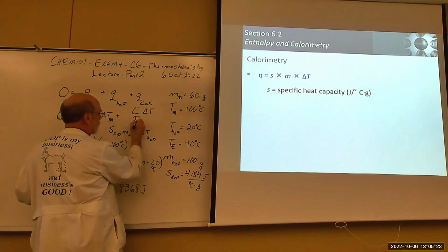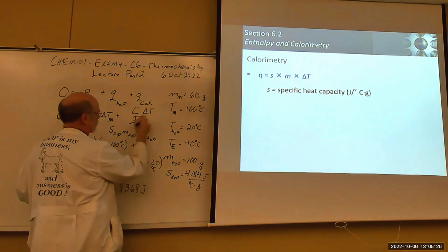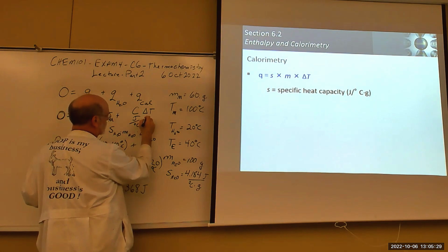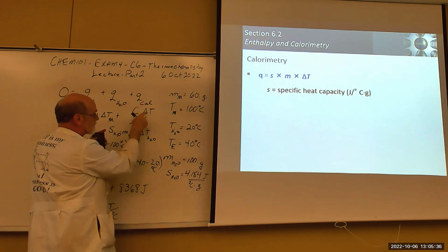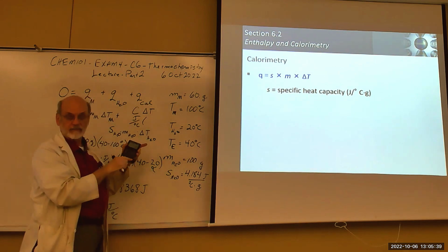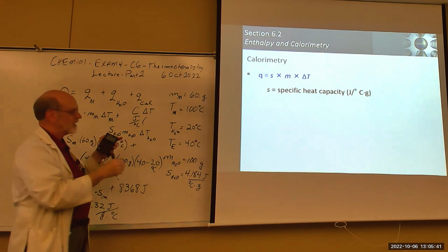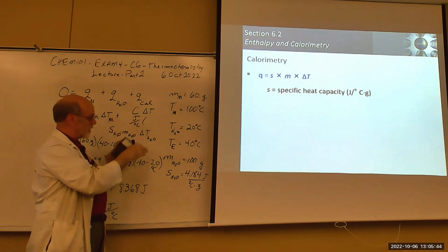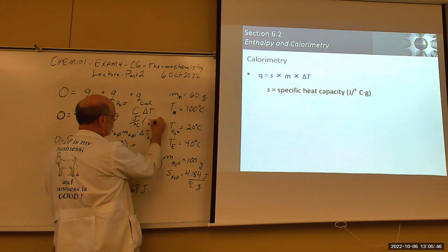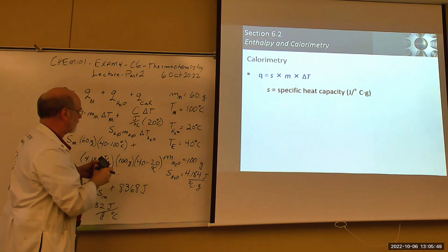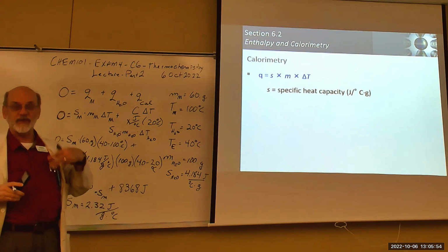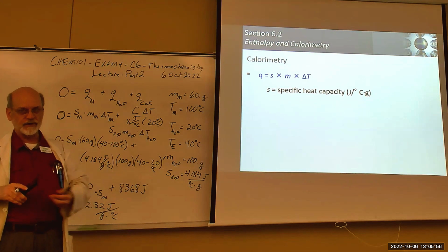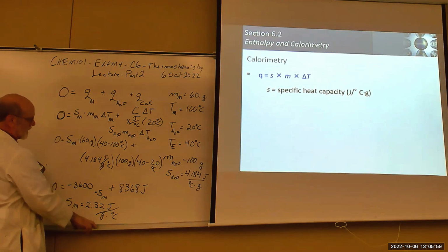So this is going to be joules per degree C. No, excuse me, yeah, degree C. And then the temperature change would be, well, we don't know. But it's usually, this temperature change is usually the same as the water, right? Because before you put the metal in it, the calorimeter is at the same temperature as the water. So this would be another 20 degrees C. But what we don't know is that value. That's why you have to determine that first before you do the rest of the experiments. Okay.